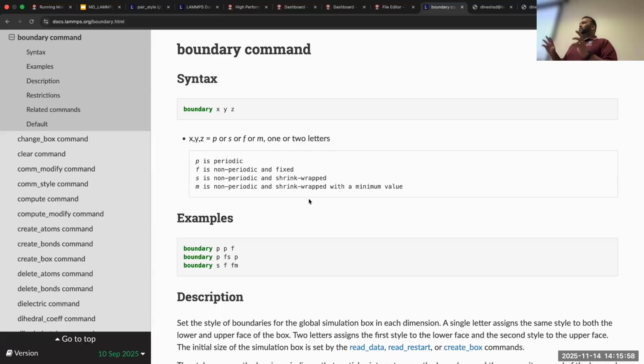What that does mean, it's not like a magic thing. Think of, you have a central simulation box. When James loaded the system and showed it to you, you see one central simulation box, but there are infinite periodic boxes or mirror images. Think of there is a central box and there are mirror images of those boxes all around, right? So in essence, when we say periodic boundary conditions, we are actually defining an infinite medium, right?